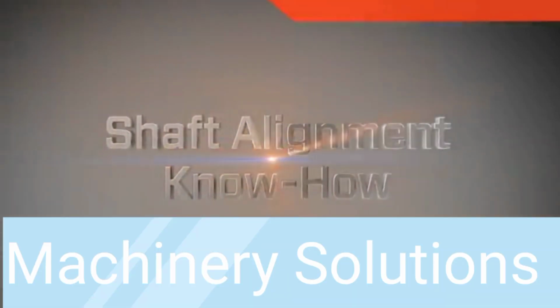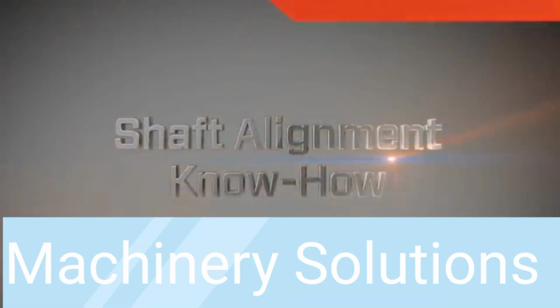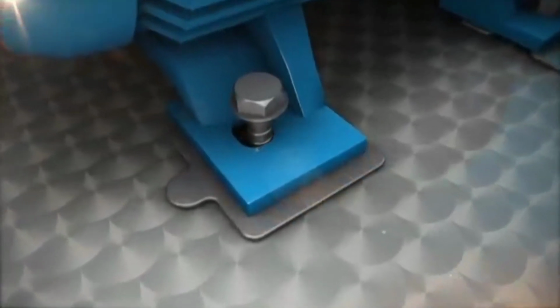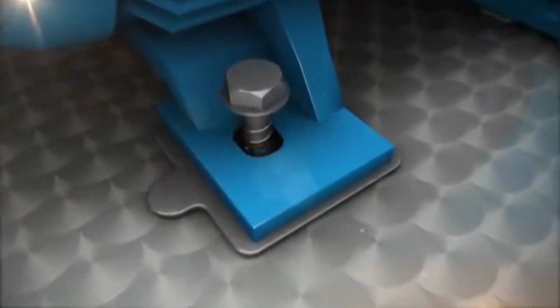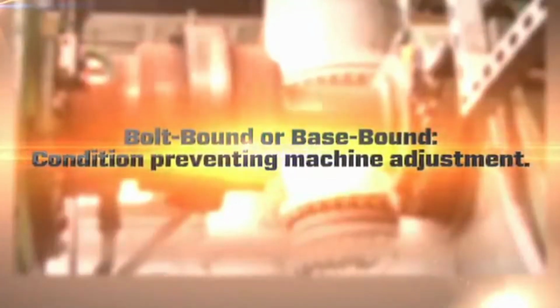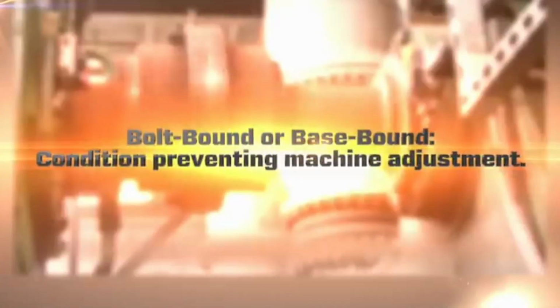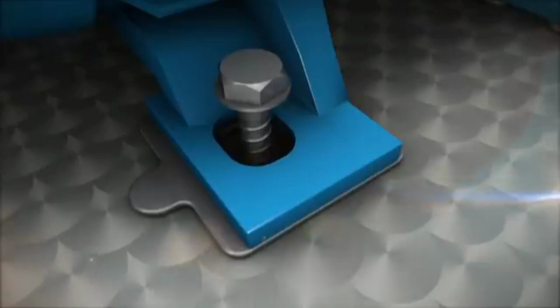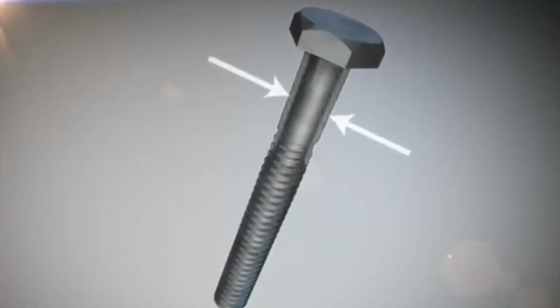Shaft alignment know-how: bolt bound or base bound. A common problem we encounter when doing shaft alignment is to become bolt-bound or base-bound. This is defined as a condition that prevents a machine adjustment from being accomplished because of insufficient clearance. Common solutions to being bolt-bound are: increase the bolt hole size in the machine foot, reduce the shank diameter of the anchor bolt, drill and tap a new hole in the base,